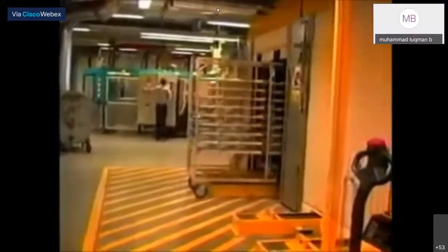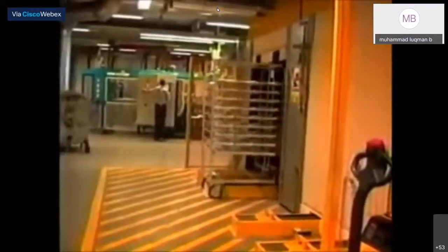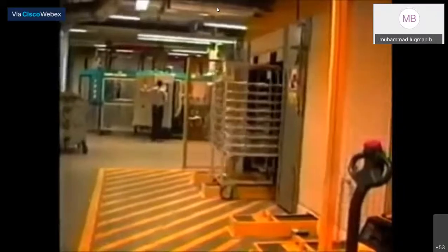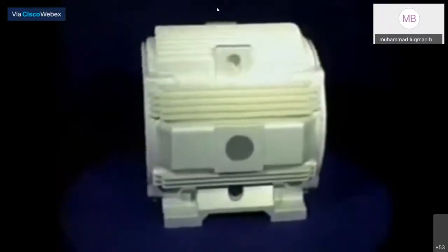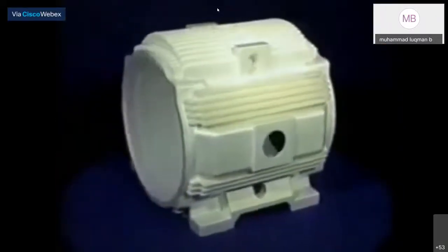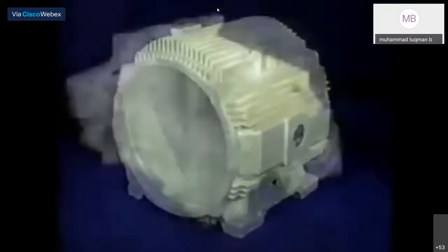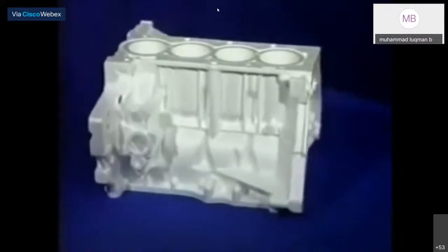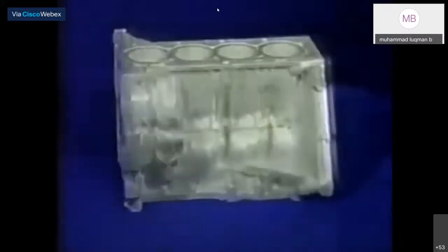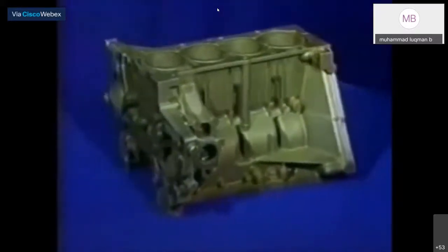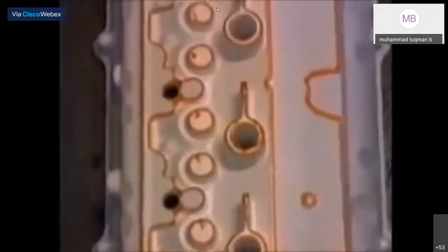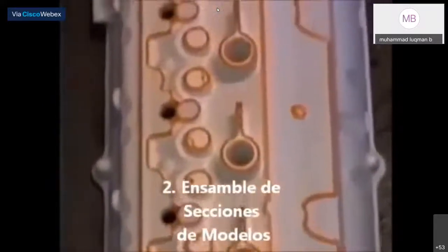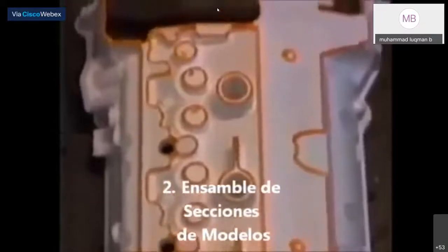Foams are normally aged, usually in a controlled warm air oven, to stabilize the dimensions. Foams can be molded in one piece, sometimes using movable pulls. Multiple pieces can be glued together to form extremely complex parts with internal passages and details sometimes not feasible in other processes. Gluing is normally done with special hot melt glue printed on the parting line between foam slices.